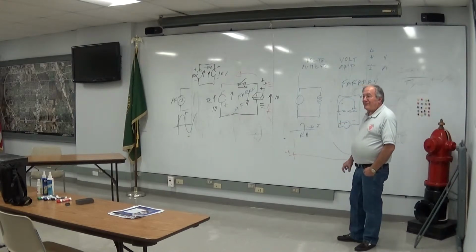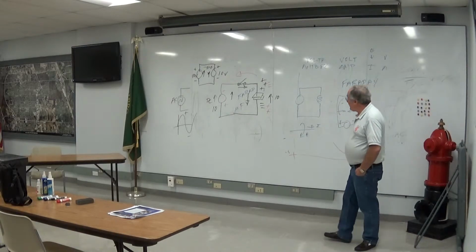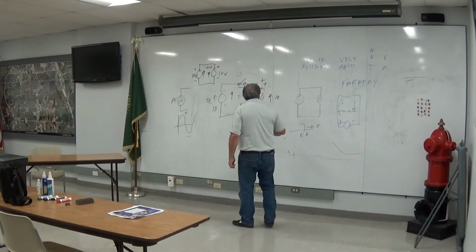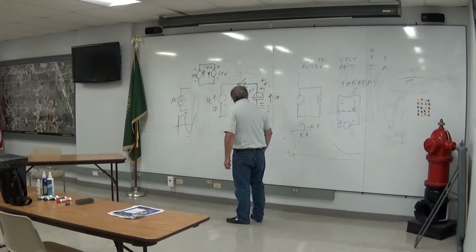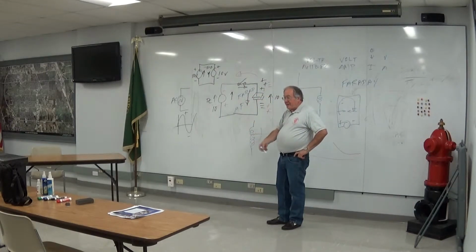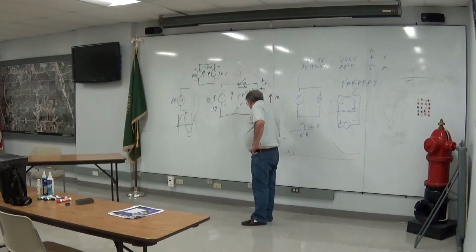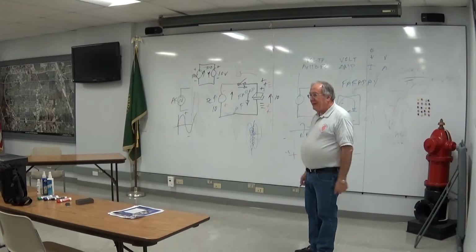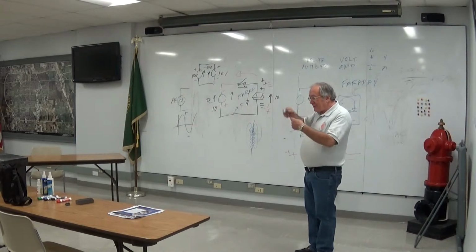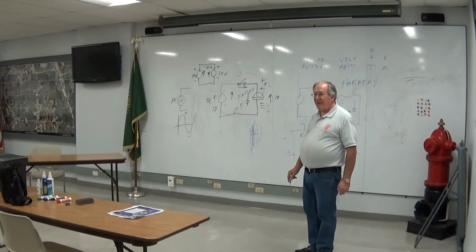Okay, so Michael Faraday used this principle that current flowing through a wire will make a magnetic field appear. What you have with this coil, which I spoke of, this inductor as I would call it, is you put another and another and another winding, and each one produces its own field, and they all add up and you get a bigger field. The more times you wrap the wire around the coil form, you can produce a coil. So if you want a bigger magnet, more windings. The turns that you have determine the strength of the magnetic field.